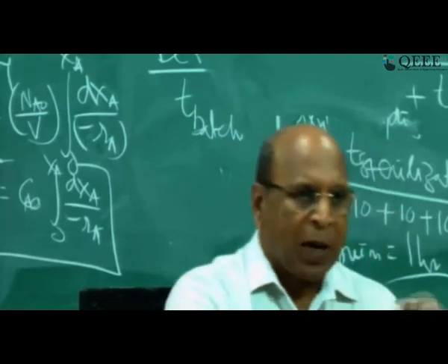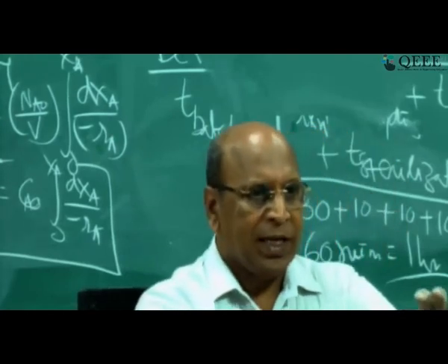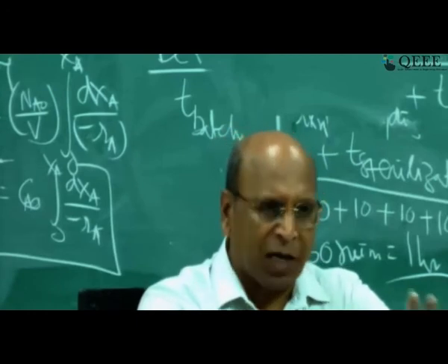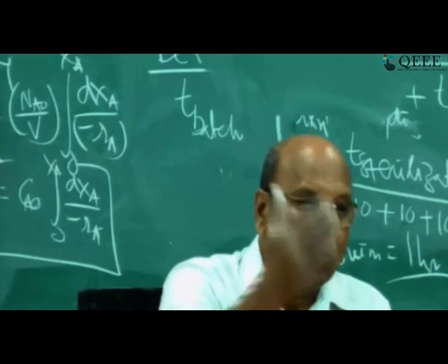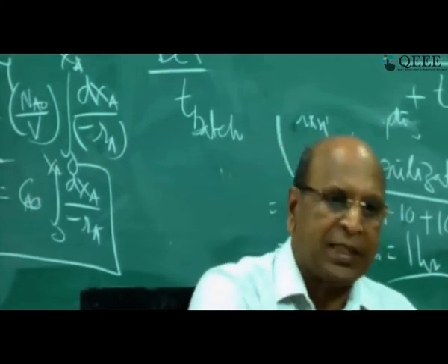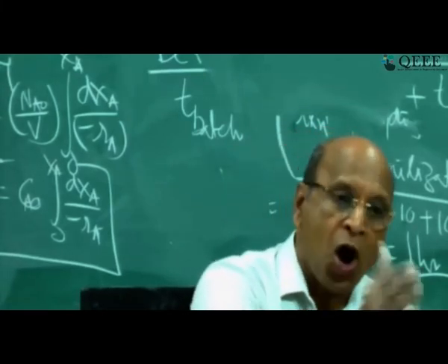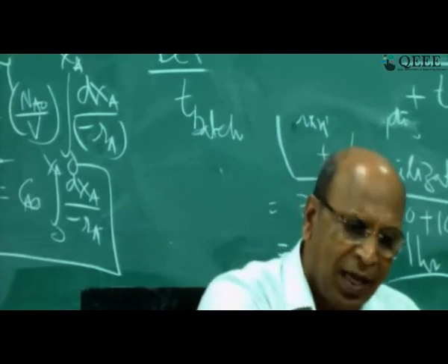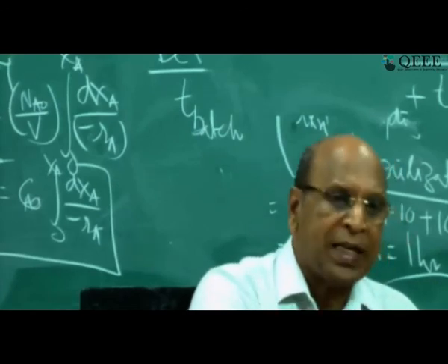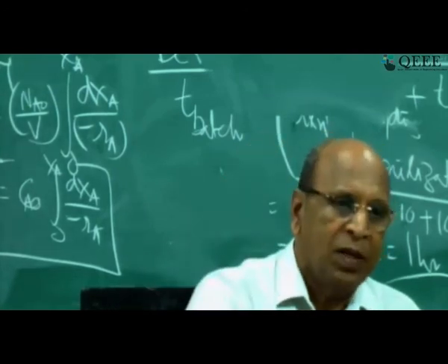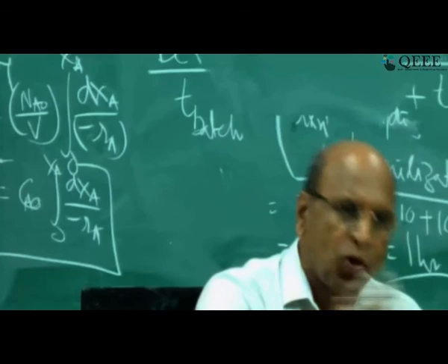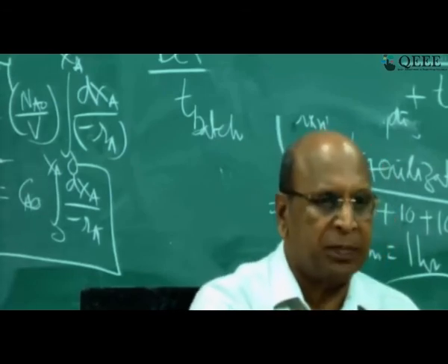So that is why plug flow reactor diameter is generally 3 to 4 inches, or maybe 5 and 6 inches maximum, and then you can maintain those velocities and radial mixing infinity, axial mixing equal to 0, all that for gas phase reactions as well as liquid phase reactions if they have very fast reaction. Fast liquid phase reactions also can be conducted in plug flow reactor.